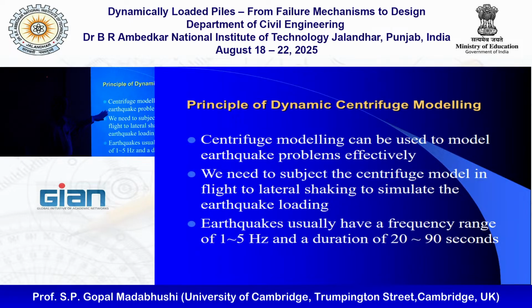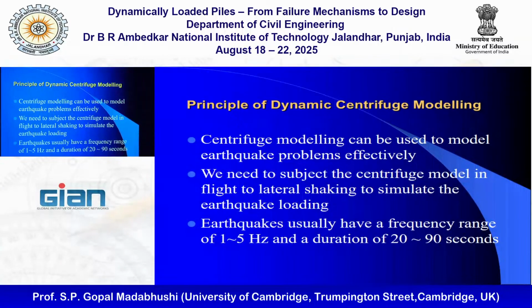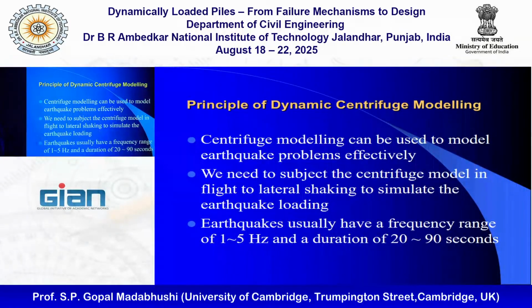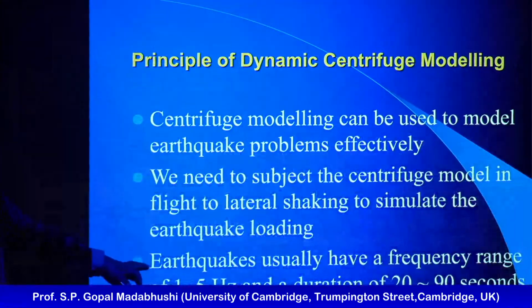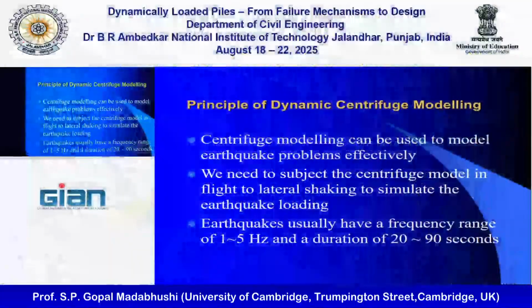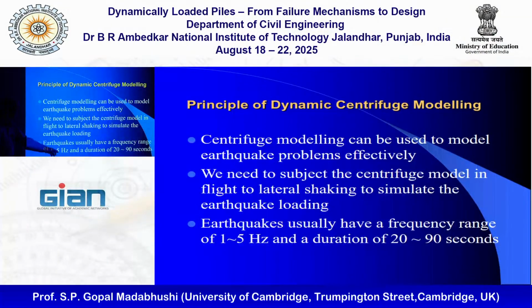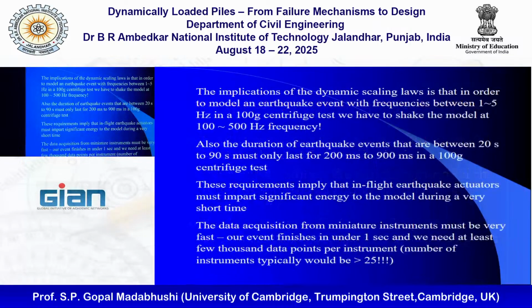If you want to model the earthquake problems effectively, we need to subject the centrifuge model in flight, while it is spinning, to lateral shaking to simulate earthquakes. But compared to real earthquakes, which have a frequency range typically between 1 to 5 hertz and a duration of 20 to 90 seconds, a minute and a half is about most earthquakes, the scaling laws now mean that, say if I want to do this test at 100 g, I need to shake my model at 100 to 500 hertz.